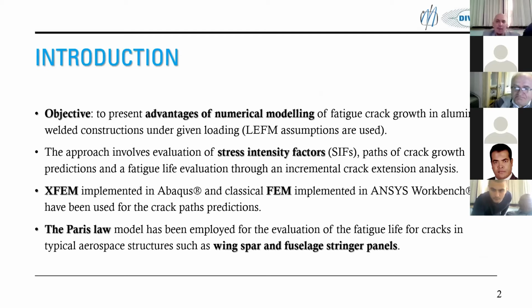Advantages of numerical modeling of fatigue crack growth in aluminum structures, especially welded constructions, under given loading using assumptions of linear elastic fracture mechanics. So all these simulations are based on evaluation. Evaluation of the fatigue life is based on evaluation of stress intensity factors and paths of crack growth predictions, which we can do using numerical methods, especially the finite element method and the extended finite element method.